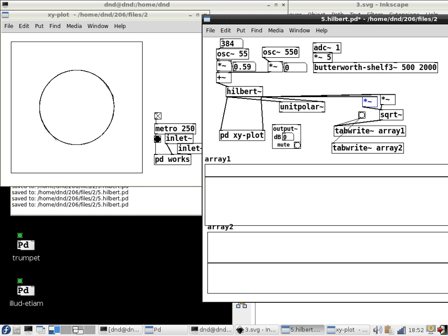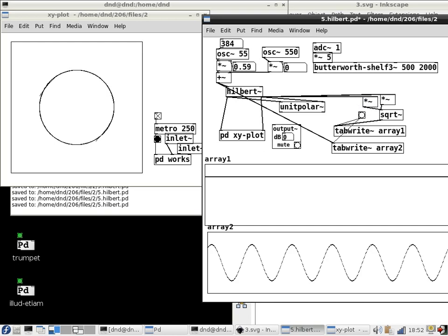Also, if I want to, I can figure out what the phase of this thing is. Okay, so let's go back to having a graph of the sinusoid that we're doing this to, so that you can marvel at how I could get this thing in and get this out. Right? Okay, so now what I'm going to do is see if I can get a hold of the phase. Now, phase is equally nasty because even if I knew the amplitude of this thing, which I do if I've done that part, still, if I tell you what the value of the sinusoid is, there are in general two possible values of the phase.